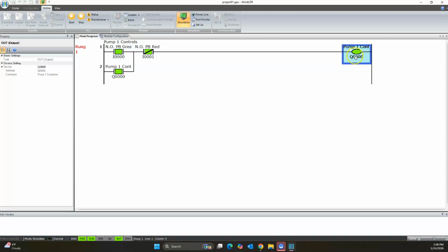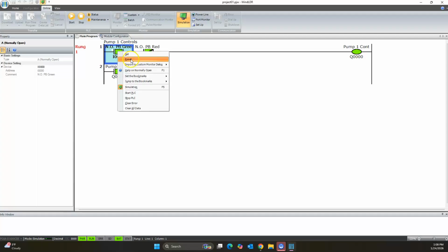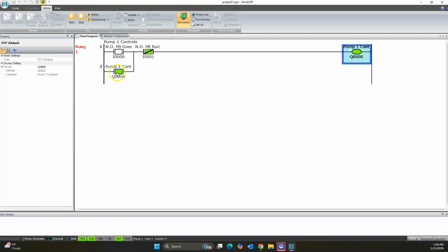Pump is on. Output is high. We should see 24 volts here now if we measure it. I'm going to let go of this button, and I'm just going to reset it. And lo and behold, because this changed states, it also made this change states. So that make instruction, when this bit became a 1 or true, the make instruction made logical continuity, right? So it followed what its name suggests. So make instruction makes continuity when it is true or a 1 or high. A break instruction subsequently breaks logical continuity when it is high or 1 or true.